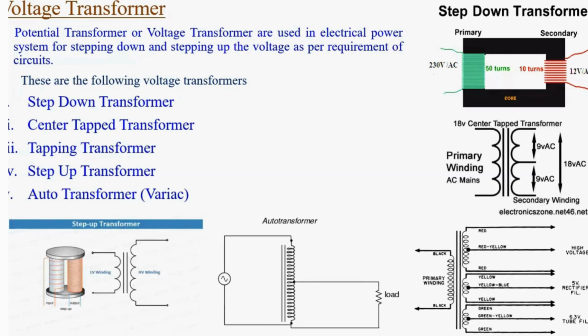But why do we call it center tap? Because we divide exactly in half. One more terminal comes from the middle of the winding, which divides the complete winding into 2 parts. That is called a center tap transformer. Then you have multi-tap transformers. Just down below, you can see the primary is 1, and on the secondary, there are a number of connections coming out.